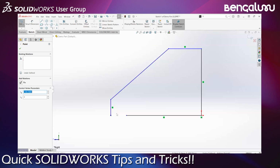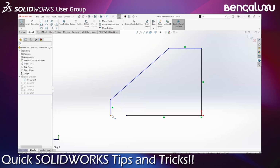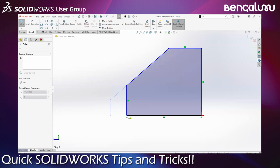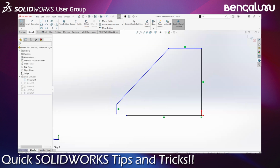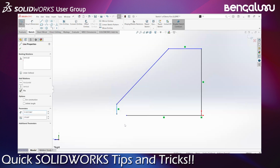In those cases, typically what users do is select the line, or sometimes even delete the line, or delete the relations and do all those things. That's not required. You can simply right click and say detach segment on drag, and whichever point you drag, you see that it drags without changing the relationship with the other line. So this is detach segment on drag. Whenever you don't want it, you can just switch it off.